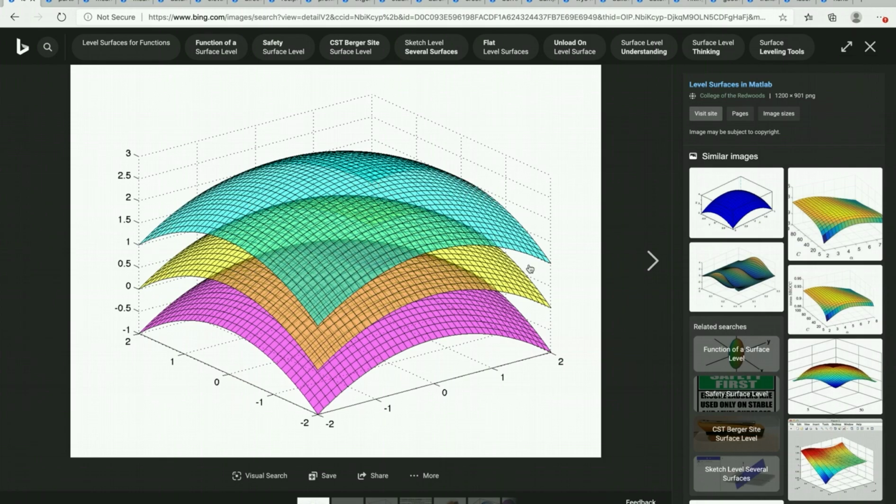Therefore, if there is a large distance from this point to this point, and we view it through a telescope, it is not a straight line. It is refracted. So it is not viewed as a horizontal distance, but there is refraction, a bend. There is a bend in what we see because again, the Earth is not a flat surface.